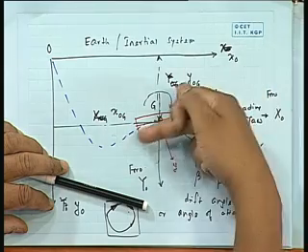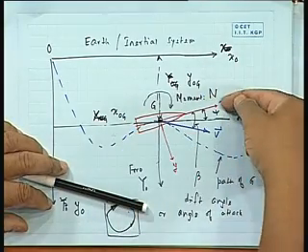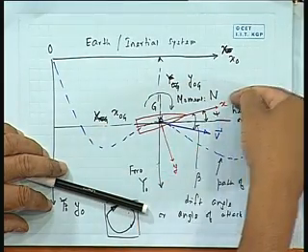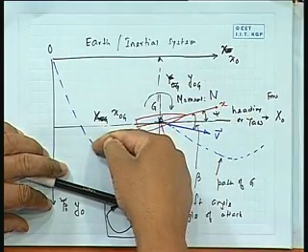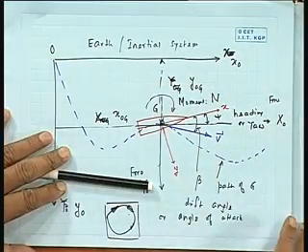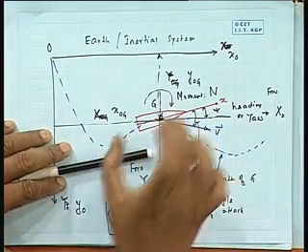Think about the logic again, the physics behind it, and why we want to change to another system. If the ship was going along x, then by inspection it would be much easier to find the force along the small x axis and small y axis. Along the small x axis the force would be the resistance force, and along the y axis it would be the sway direction force, because sway direction is defined that way. That way it is not dependent on the instantaneous position of the geometry.